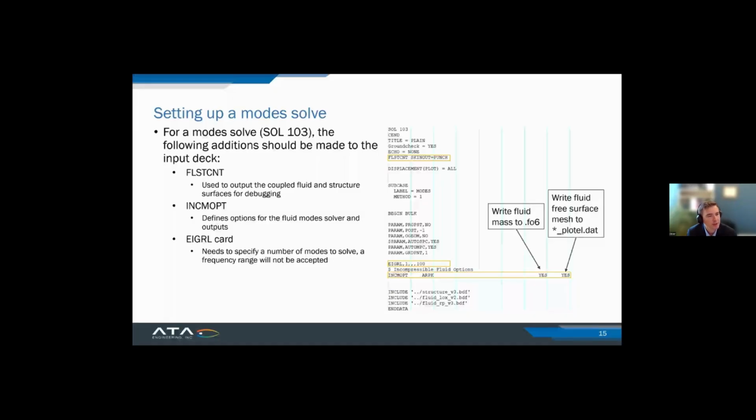Related to radius in the tank, sometimes your GNC team will just require it. They want to know about slosh because it's relevant for their algorithms. From a loads perspective, if you have a super stiff tank, several inches of steel in a small diameter, then yes, maybe it's not that relevant to look at slosh dynamics in there.